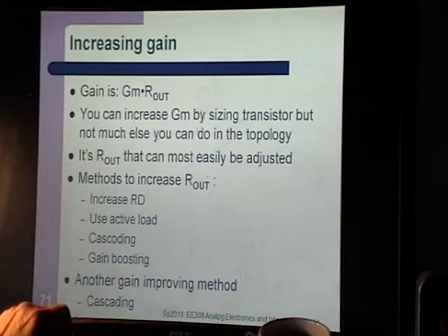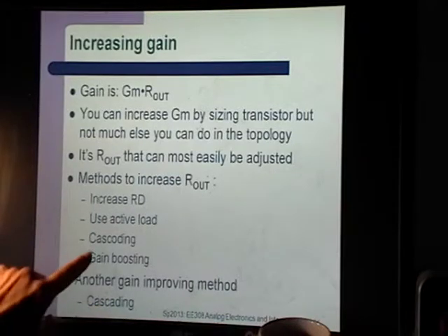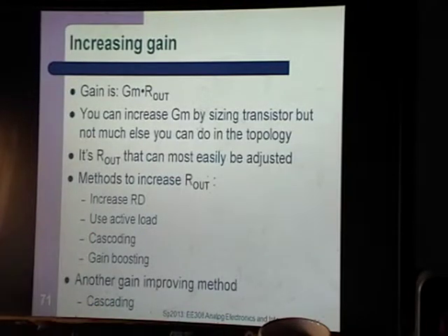The problem is that you get lots of poles, the frequency response is more complicated, and now you have 4 amplifiers to bias instead of 2. The design just gets a little more complicated.